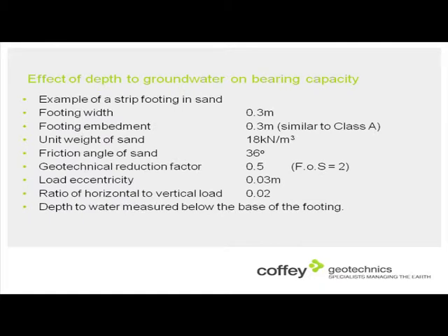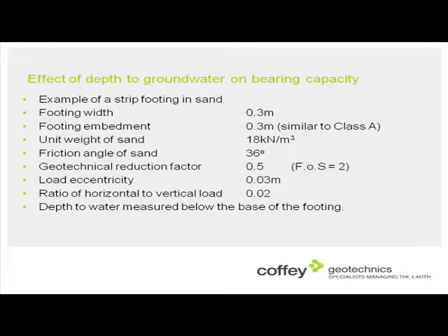So what does groundwater do to bearing capacity? Remember we talked about if the strip footing's not tied to the slab, we need 100 kilopascals. Well, I've got some complex calculations for Deborah's benefit. She likes those. So I won't go through why I chose those parameters, but when you look at bearing capacity, you look at the width, the depth of embedment of the footing, the soil properties, whether the load's centrally located on the footing or slightly eccentric, whether there's some horizontal load from wind loading and those sorts of things.